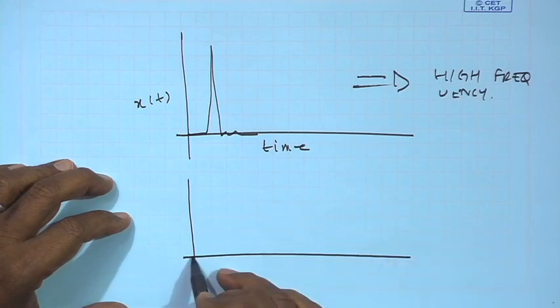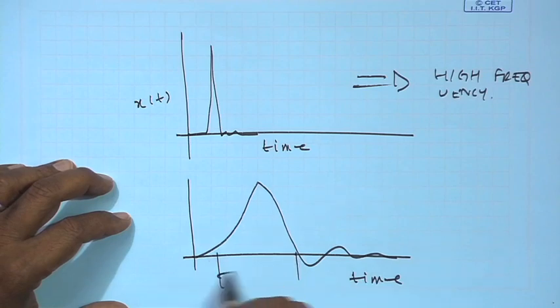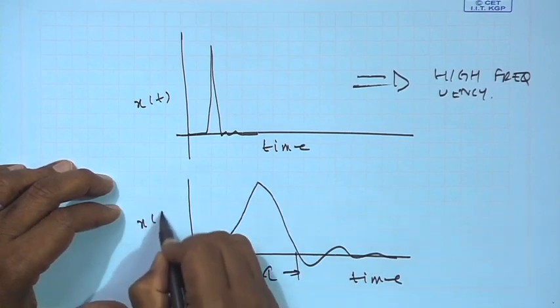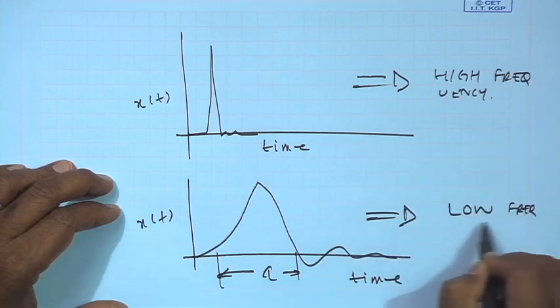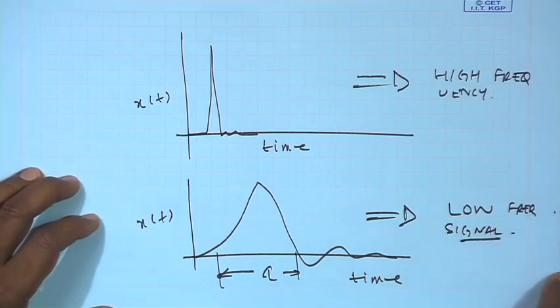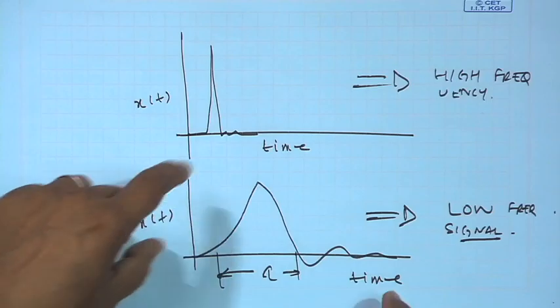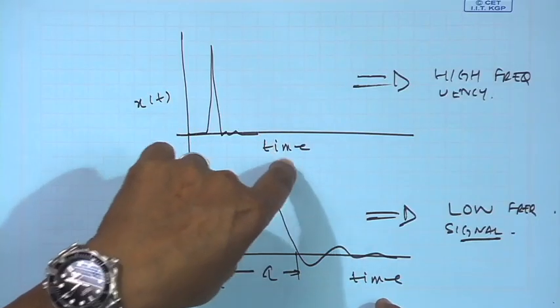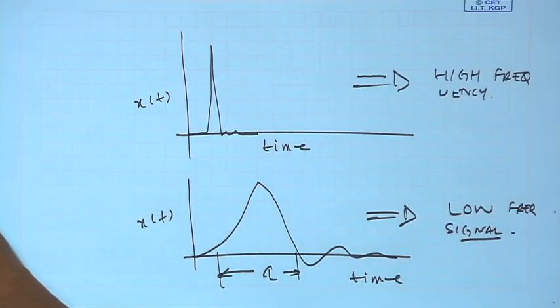So, that means if the time duration of the impulse is very large, this gives rise to a low frequency signal. So, wherever you have impacts occurring, things falling or dropping in machines, if there are metallic components, you will hear a lot of impacting metallic noise which is high frequency, as opposed to something falling like a thud in a very damped environment. You will have a large time period, so a low frequency signal. Just keep that in mind.